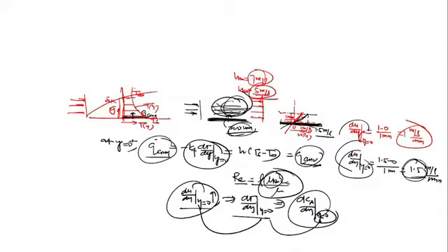Are you getting the point? Increasing the velocity gradient at the wall also increases the temperature gradient, and as the temperature gradient increases, it also increases the heat transfer via conduction through the wall. Now the rate of heat transfer via conduction to the wall takes place faster, yes or no? So ultimately, by increasing the velocity, what increases?